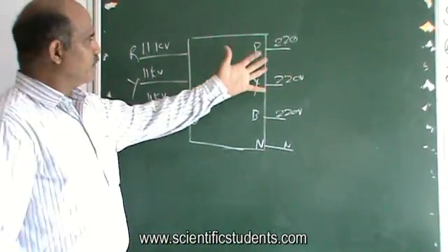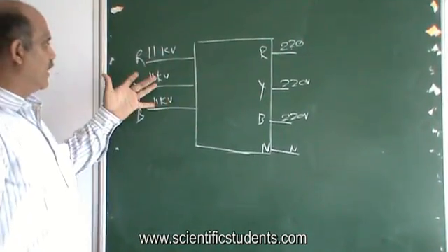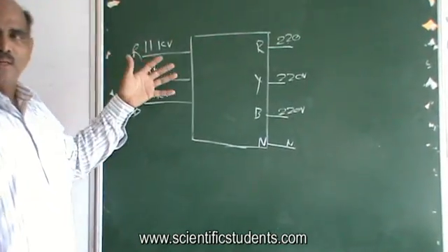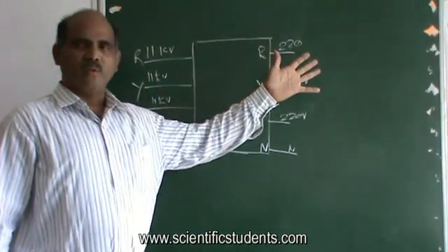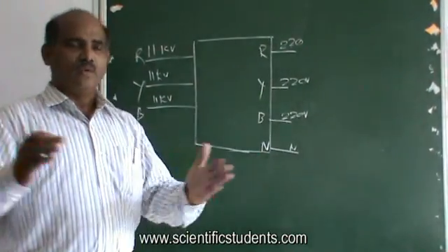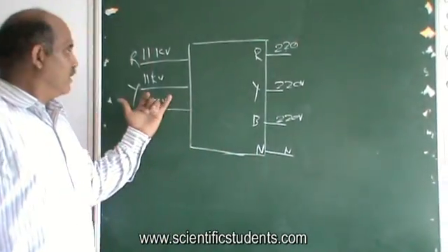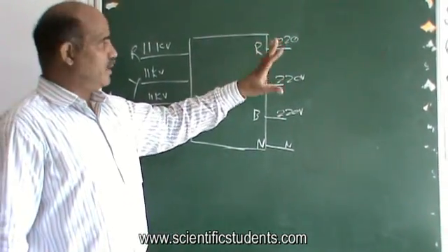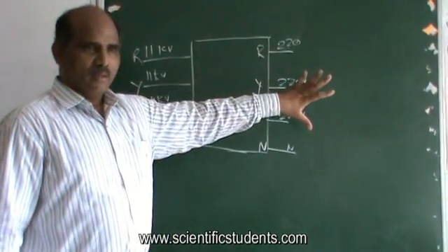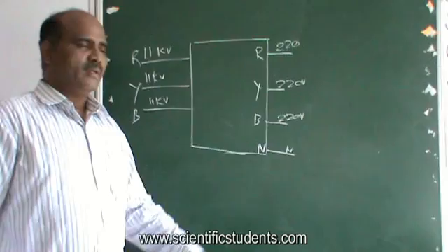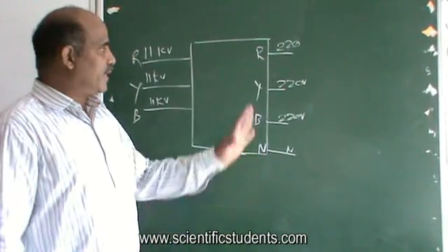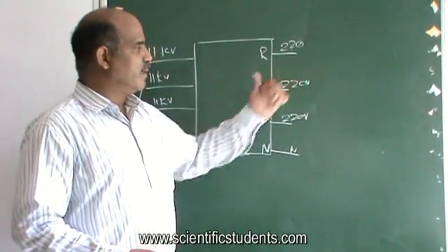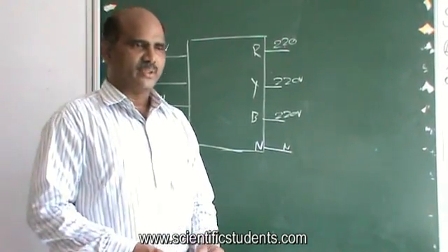So, the output voltage of this transformer is proportional to the input voltage. If it is less, the voltage will go down. If it is more, coming from the 33 kV transformer, the secondary voltages go up. That's the voltage fluctuation because of the input voltages. Another important point is the load put onto the secondary of the transformer. If the transformer is capable of handling only 100 kilowatt and people put more load on those phases, the voltage drops drastically.